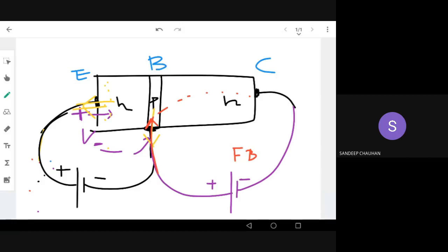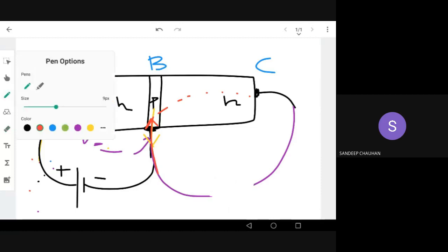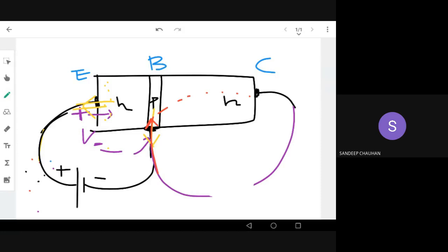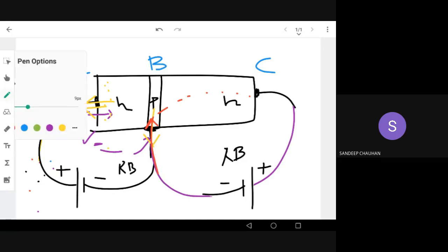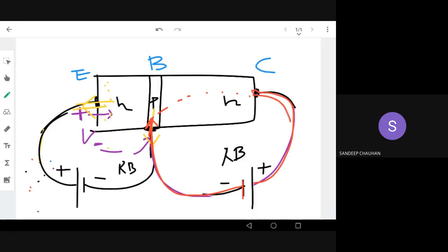Okay, this also has to be reverse biased. That means this should be positive and this should be negative. So plus and minus. So this is also reverse biased. So here also there is no current actually, because this P region is connected to negative bias and the N region is connected to the positive side.